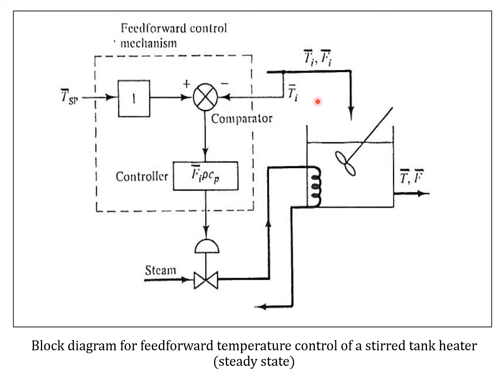Okay, the set point with respect to the measurement of disturbance times this. So this is the Q that we want. If any disturbance comes in, it is measured and taken care of through the manipulated variable, and basically rejected before it comes and affects the system here. So this is basically feed forward to make sure the temperature is not affected by the disturbance coming into the system.